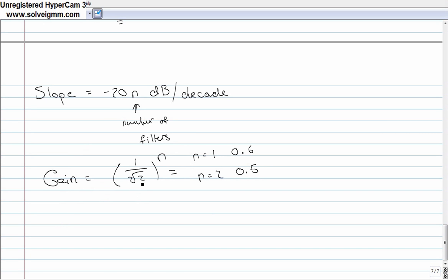It's also going to start moving back. That frequency at that gain is equivalent to the cutoff frequency you calculate times the square root of 2 to the 1 over n minus 1. So with just one filter, 2 to the 1 minus 1 is 1, square root of 1 is 1 times FC. So the frequency at that gain is the cutoff frequency.